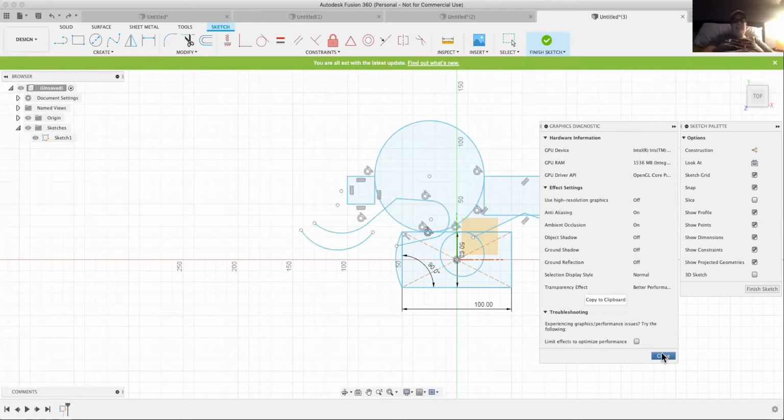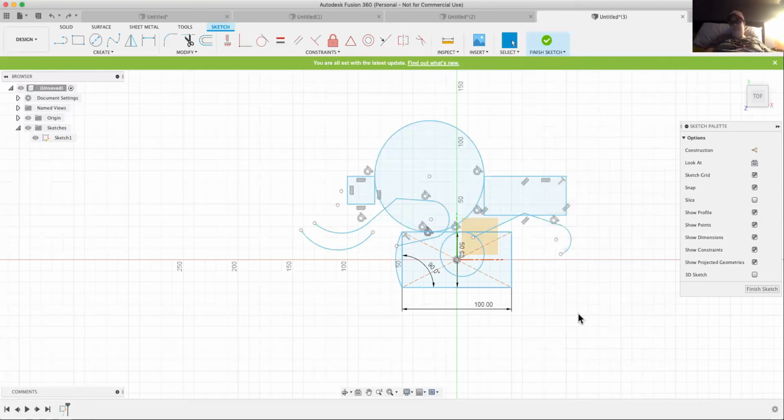Okay, so back to the driven and undriven, or driven and driving. Whatever, driven and driving. When it was 90 degrees, because it was driven, you couldn't change it. They were just showing you the dimension, basically. Correct, and saying there's nothing you can do about it. And then you got rid of one of the constraints, and then you made it a driver and made it any degrees you want. Right. Gotcha. Okay, cool. Thank you.